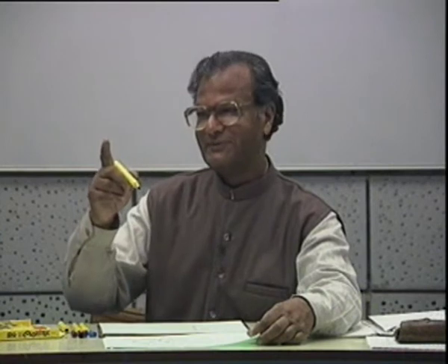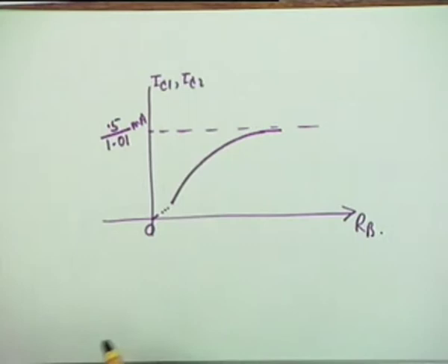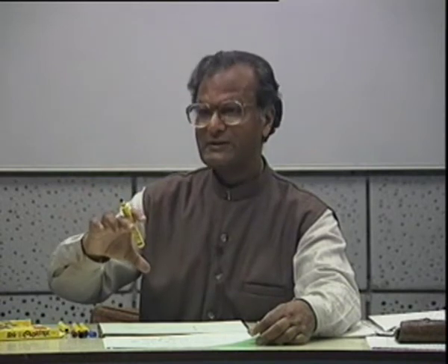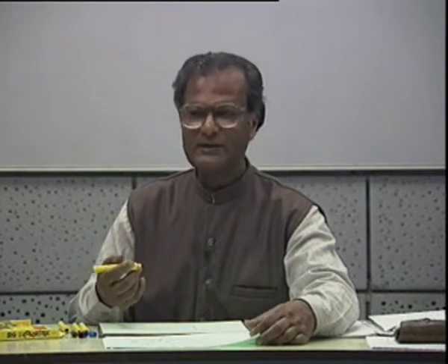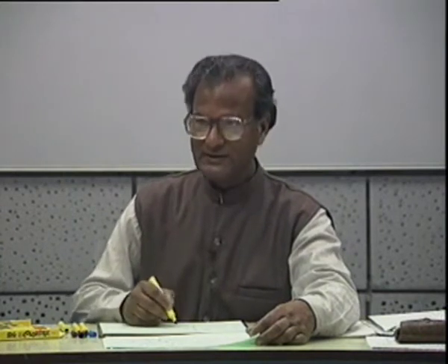Agreed, all of you? I will, however, leave a little dotted line here, little dots, because in this region it is a bit uncertain. When it actually goes into the active region, you are quite correct that if it is a perfect short circuit, then the current has to be 0. Because VBE equal to 0, exponential VBE by VT is 1, that minus 1 is equal to 0. That is perfectly all right. The nature of the curve would be different in this region, yes.